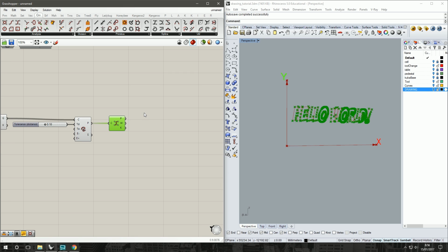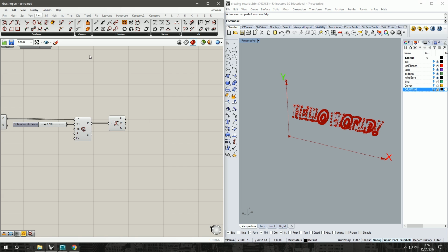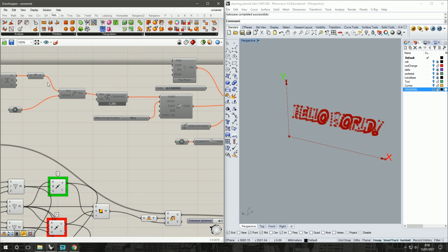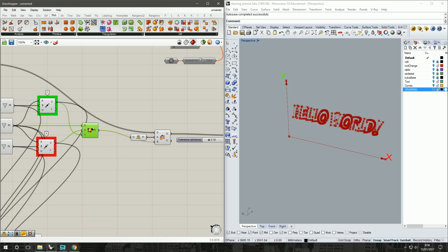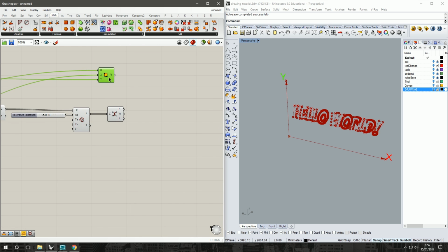Now this is where the tricky part is. These points are just referencing the world X and Y. So here, they're the standard X and Y. If I put on planes, if I use these points just as we did here with the XY, they're using the standard world XY. We want to use our plane here, so if we click and hold down Alt, move down our new constructed plane. Instead of the origin point being here, we'll use all of our new points. And there we've got our points set up in the correct orientation for our drawing.